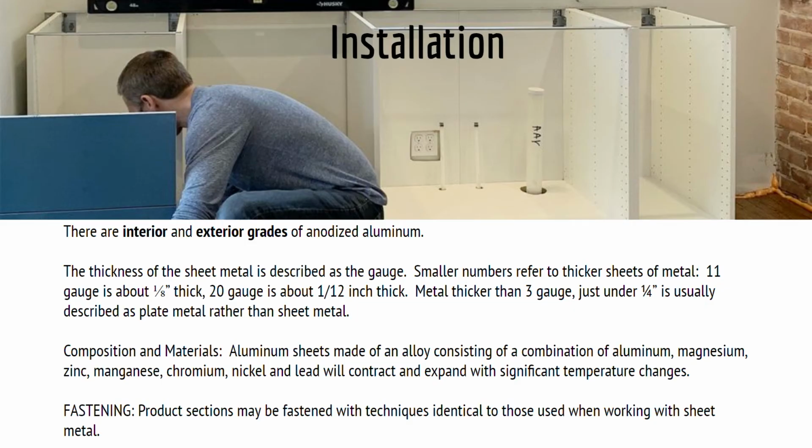There are interior and exterior grades of anodized aluminum. The thickness of the sheet metal is described as gauge. Smaller numbers refer to thicker sheets. For instance, 11 gauge is about 1/8 of an inch thick, while 20 gauge is about 1/12 of an inch thick. Metal thicker than 3 gauge, just under 1/4 of an inch, is usually described as plate metal rather than sheet metal.